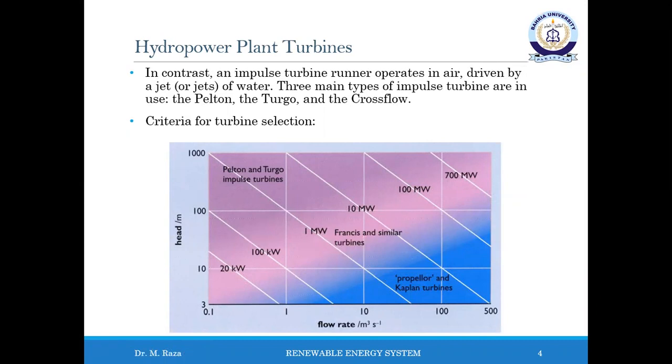Note that effective head is not the only factor determining the most appropriate type for a given situation. The available power also matters. It should be noted, however, that the boundaries are by no means clear cut, and other technical issues or criteria such as cost, simplicity in manufacturing, or ease of maintenance can lead to a choice outside these ranges.